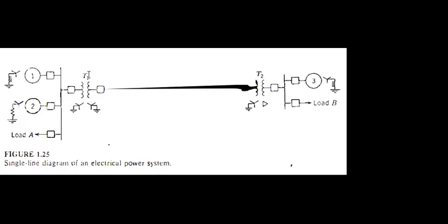There you have the transformer which has YY configuration, and in the generator you can see you have some reactance in the ground path as well as some resistance ground. But for the transformer, you have solidly grounded Y configuration. So these are different options you may have sometimes.